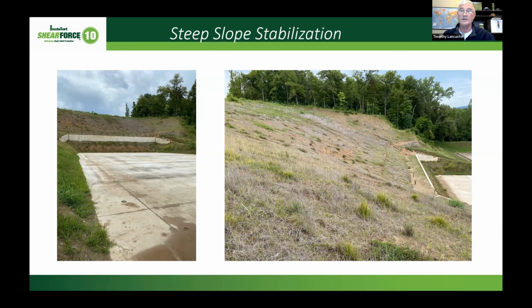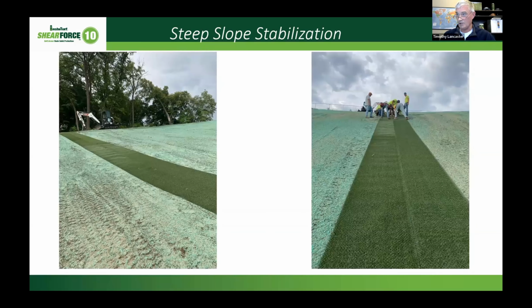And 2 years later, they just had a lot of erosion, a lot of rilling. A few pretty good sized gullies had formed. And I guess 2 years ago, they were having a general visit the site late that fall, and they said they had to get it cleaned up. So they put quite a bit of money into actually renovating this slope. They basically regraded that slope, put a layer of 8-inch topsoil down, compacted it, and then smoothed it out really nicely.